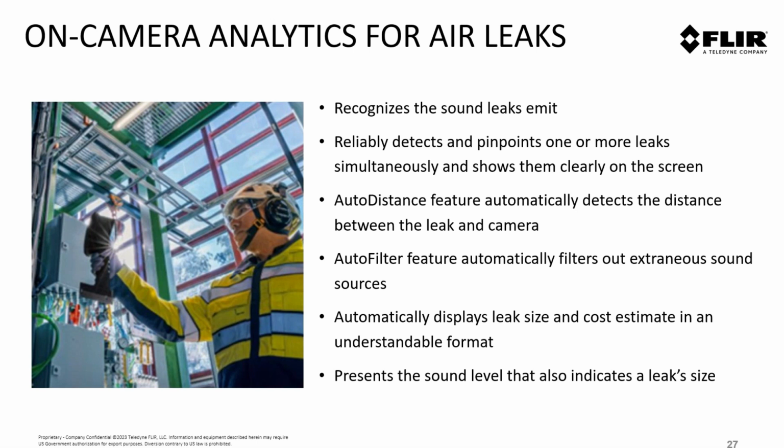The multiple MEMS microphone array will allow you to triangulate and pinpoint those specific sound frequencies, the noise being emitted by that leak, and do so in louder environments, because the sounds produced in those loud environments are happening at different ranges, where the leaks are typically in a smaller frequency range that we can pinpoint down. And then I think, John, was there one other question?